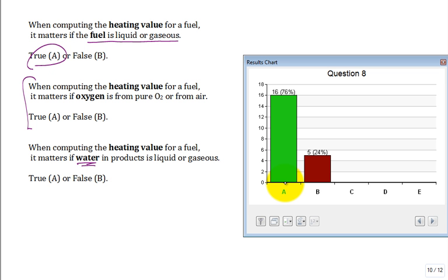So they make condensing furnaces, and the first time you hear it, you say, what was the engineer thinking that designed and proposed that? But that's the highest efficiency furnace. They'll actually try to take the products out at 25 degrees C, which is cold, which means they have to condense because it's below the dew point temperature. And when they condense, they get more heat into the home.